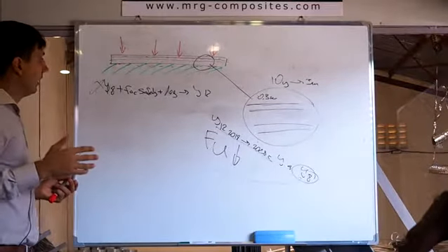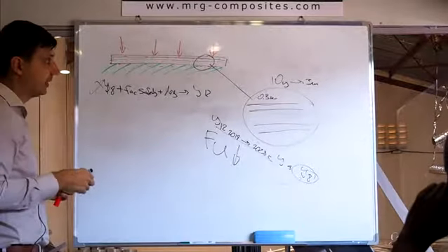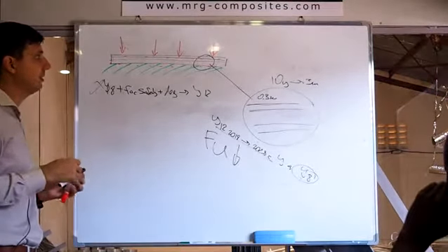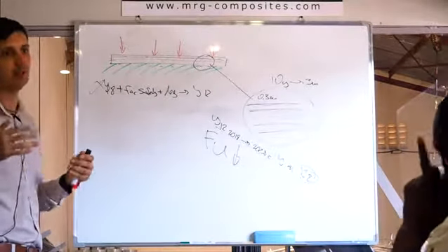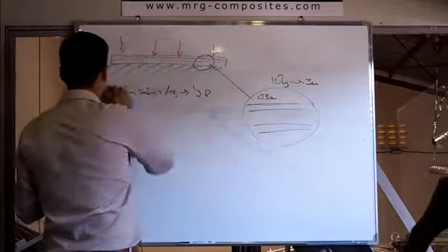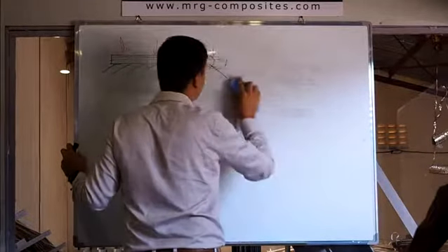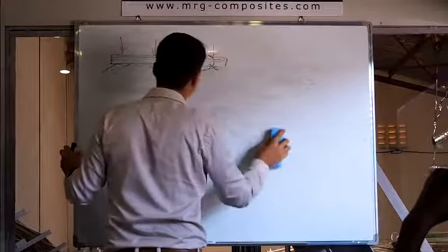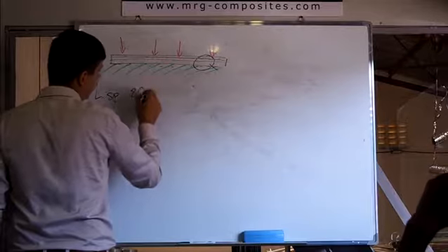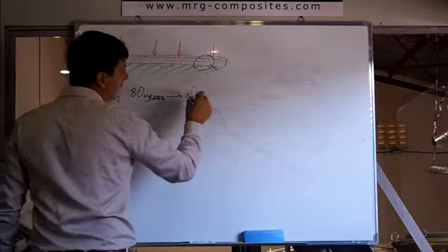So in our case, what can we tell? If we put, let's say, FRP-8, after 10 years it is going to be FRP-8, and after 20 years still FRP-8. So there is almost no degradation. Why almost? Because of course some degradation is still going to be there, because life is life and material is material. Yes, this material is chemical resistant, very true, but even this material can degrade. But if the lifespan is 80 years, maximum degradation is going to be less than or equal to 25% only.